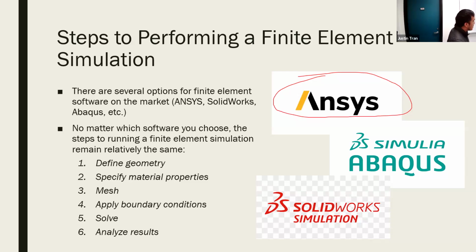So we're focusing on ANSYS because that's probably the most widely available one, the one that's most widely used in companies. But just know that the way I'm teaching this class is that the methods and the process that you're going to go through in ANSYS, you can also apply in the different softwares as well, okay? The only thing that may change is that maybe the buttons are in different places or maybe the exact order of operation may be slightly different. But no matter what software you use, you're going to follow all of these steps of defining the geometry, specifying material properties, meshing, boundary conditions, solve, and analyze, okay?